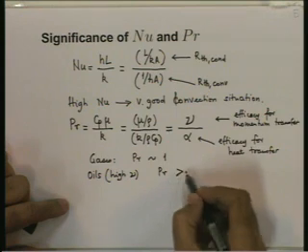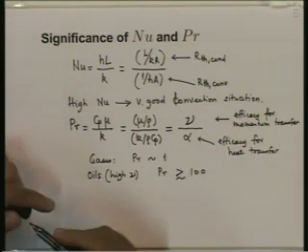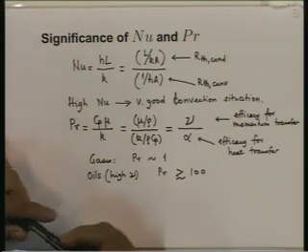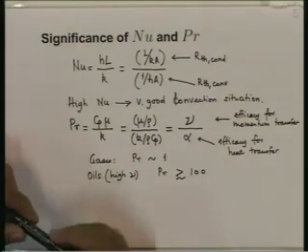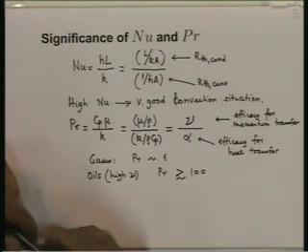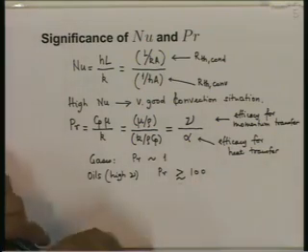You take oils, say lubricating oil, engine oil of a car. Here we have high viscosity. Prandtl number is of the order of or greater than 100. Prandtl numbers of 300, 500 are not uncommon, particularly for low temperature oil.